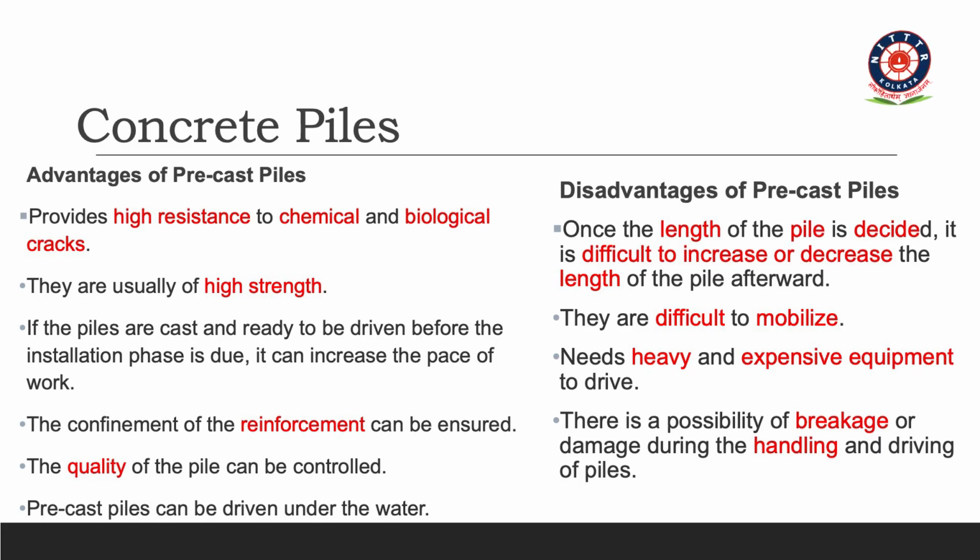And precast piles, we generally use in underwater conditions. There you can't do the bored cast in situ concept. So you will prepare the pile in the casting yard, then move it to the workplace. Then what is the disadvantage of precast? We have to understand. So the disadvantages go like this.